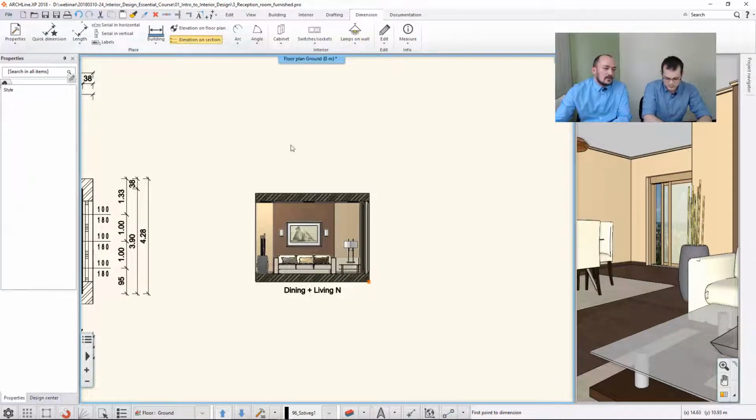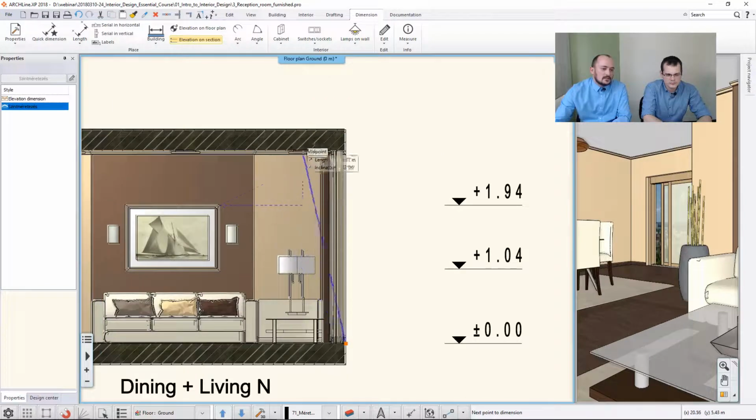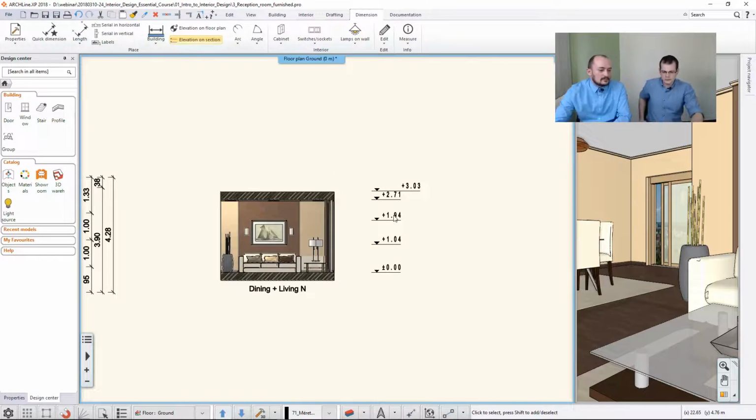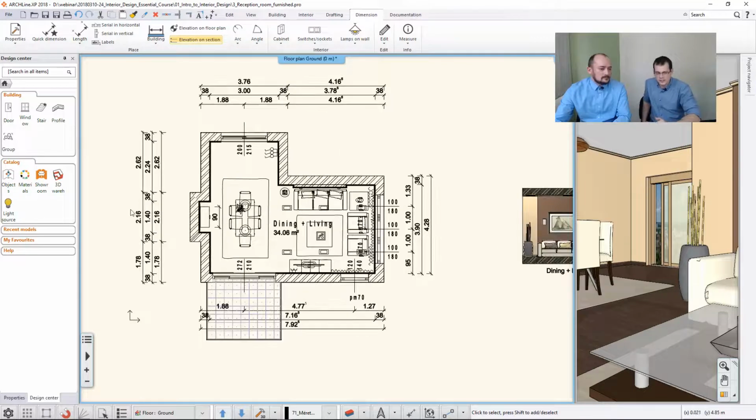but now that I have combined them, I can measure them together by using the dimension elevational section, and then I just click here, set up 0, and I just measure the bottom of this here, the top of this here, the bottom of the ceiling, for example, and the top of this item here. So I can add all sorts of information that's necessary, and then at the end I can print it to another drawing. We'll talk about these documentation things in detail at the last session of our webinar series, but let's now talk about Excels and takeoffs.